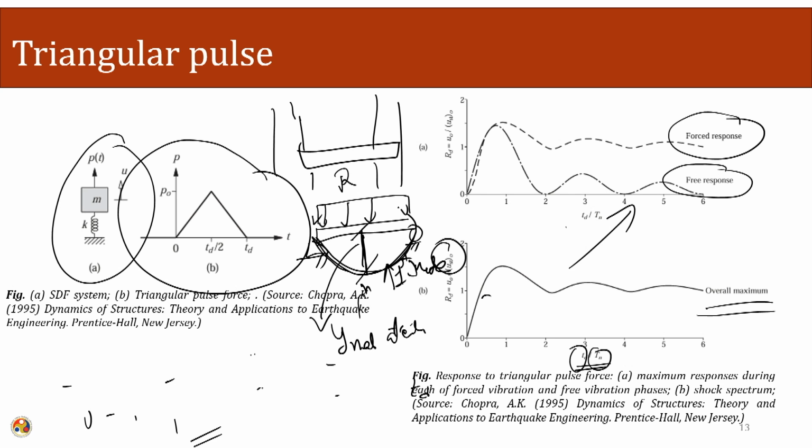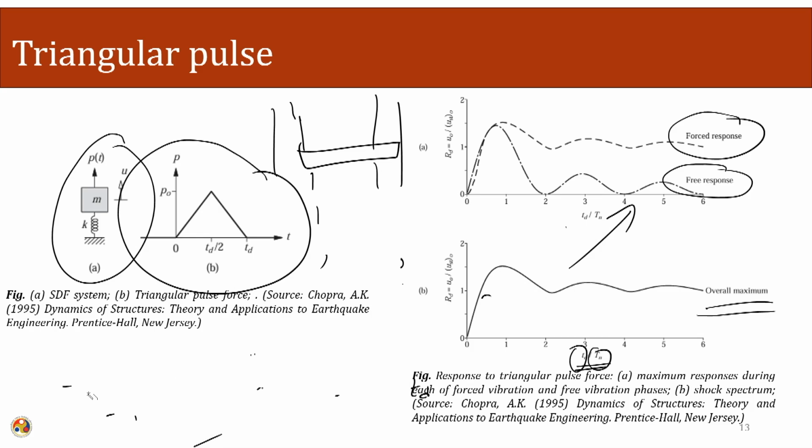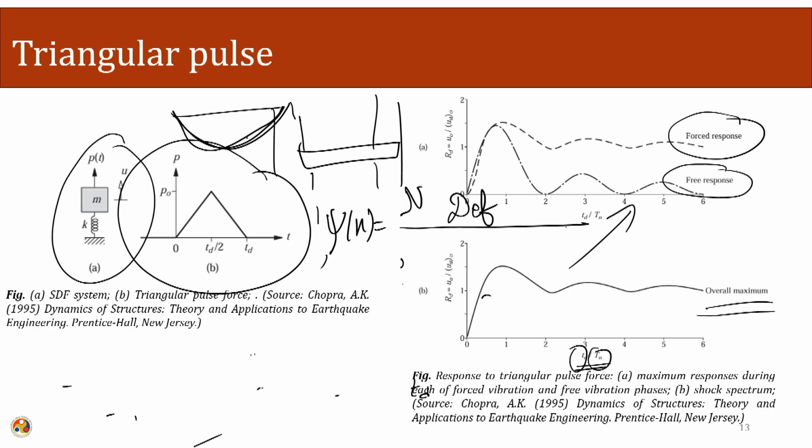So, this is our first choice of mode, that is, we are choosing the first mode and we are choosing the maximum deflection at the center. From there, we make our shape function. The numerator of the shape function is given by that particular deflection equation. In the simply supported case, it is given by the deflection equation for the simply supported case, and the denominator is given by the deflection equation evaluated at the center.